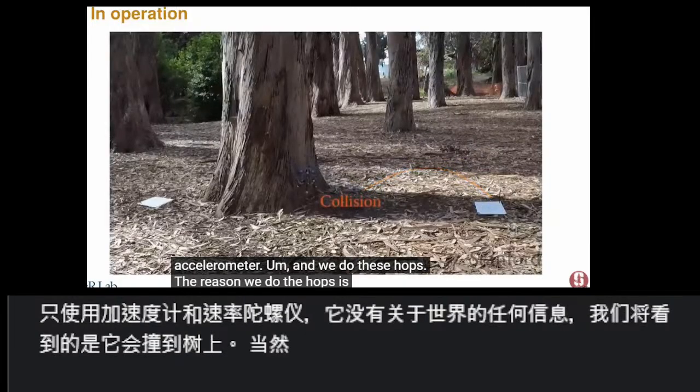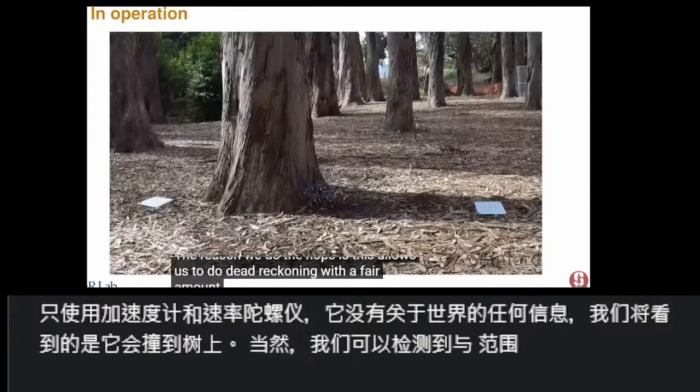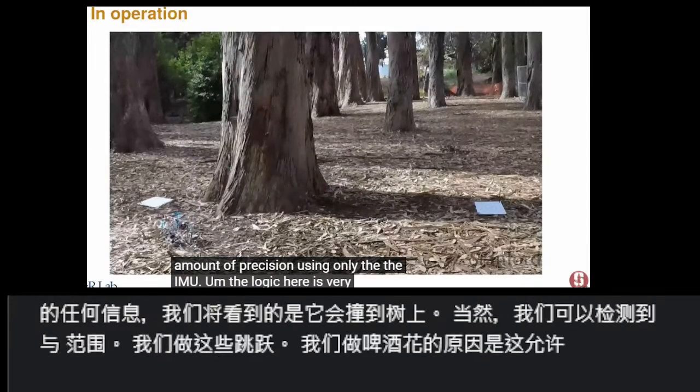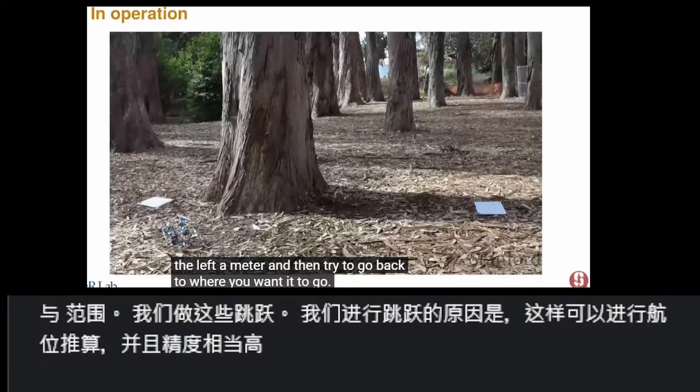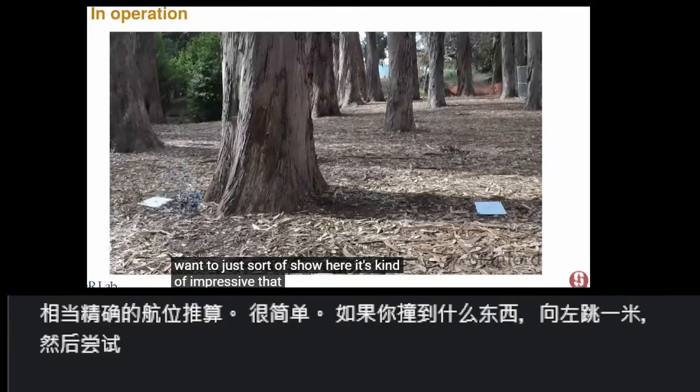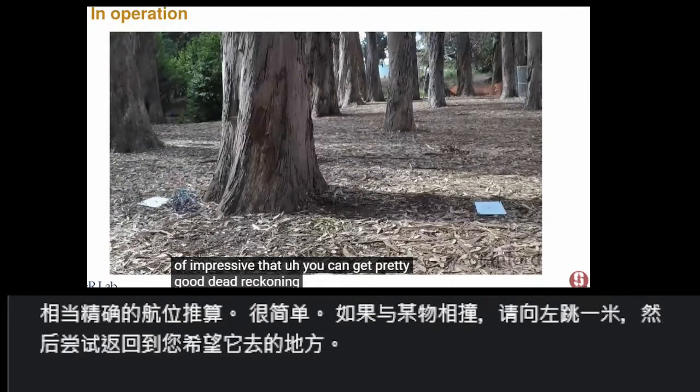The reason we do the hops is this allows us to do dead reckoning with a fair amount of precision using only the IMU. The logic here is very simple. If you collide with something, hop to the left a meter and then try to go back to where you want to go. But I want to just show here, it's kind of impressive that you can get pretty good dead reckoning from this.